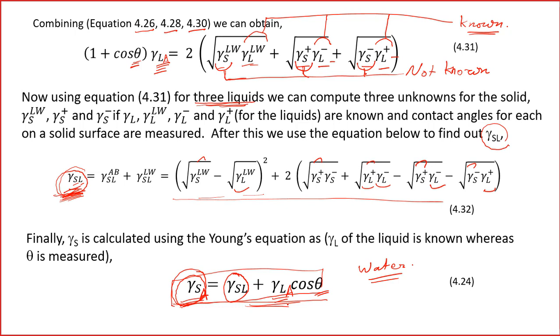So for example, when you talk about Teflon coating, by applying Teflon we are actually reducing the surface energy. Teflon has very low surface energy compared to some other materials like ceramic. So if we use a Teflon coating and a ceramic coating, the Teflon coating will provide low friction because of low surface energy and low adhesion, but ceramic coatings will not provide low friction, even though they are hard. Because it is hard, it is wear resistant, but in terms of friction it is not giving a low coefficient of friction. So it is the physics behind the friction adhesion that is acting on the solid surfaces. So this is very important.